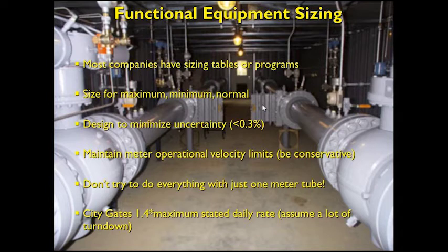One of the worst operating conditions is to try to do custody transfer measurement between two pipeline companies, and you have one 30-inch or one 24-inch ultrasonic meter. You're going to have a dispute before very long, and you won't be happy, because you find out that a lot of times that large diameter meter is operating down around 5% of its capacity for about 90% of the time, and then they have a high flow day, and then it's back down again, you know.